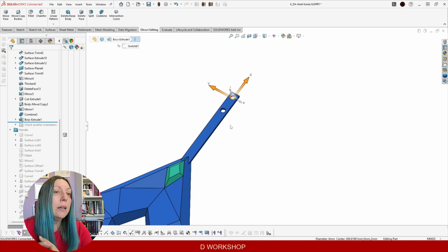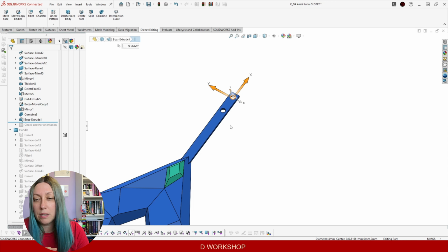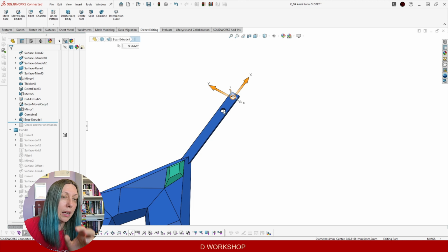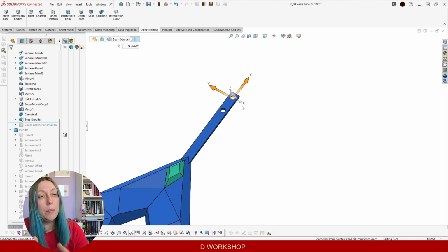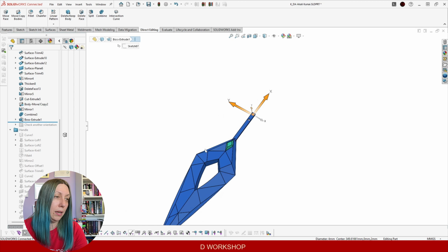Reason one, I will use the two holes to align when I'm gluing, otherwise it will slide, probably won't land in the same place. I'm using a fast glue, and for seconds you can mess it up. That's why alignment pins will come here, and these ones will also keep the blade itself in the handle once everything is ready.